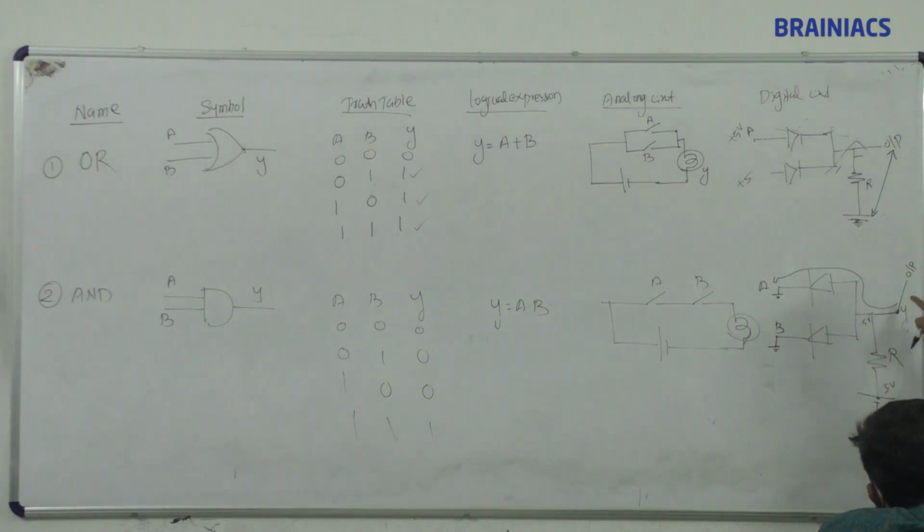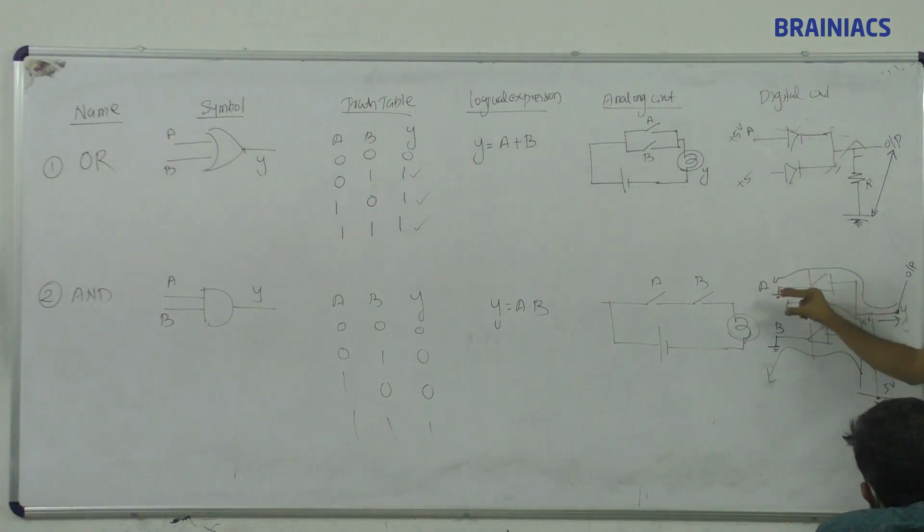The currents are going directly into ground, the currents which are going here, but there is no current flow towards the output side, because here is a high resistance path. Whenever it comes here and looks here, there is no connection, so it is a kind of open circuit, high resistance. But when it looks here, it is just like a short circuit. Correct? So current will always choose the low resistance path. Immediately current will go through this one and it will get grounded. So output will be equal to 0. Never memorize this by heart.